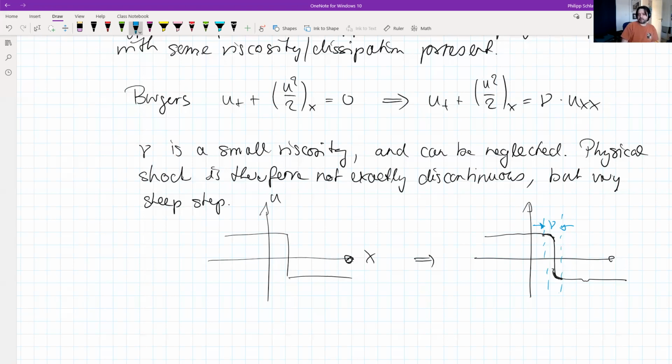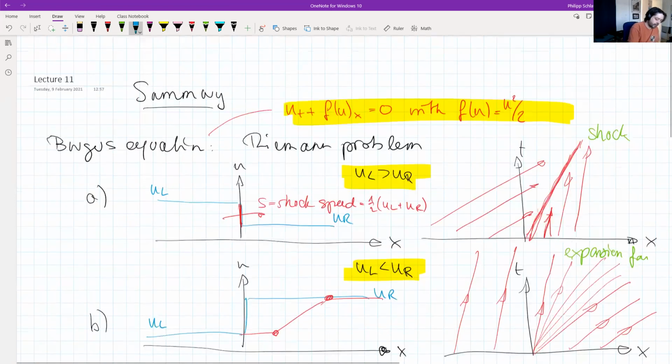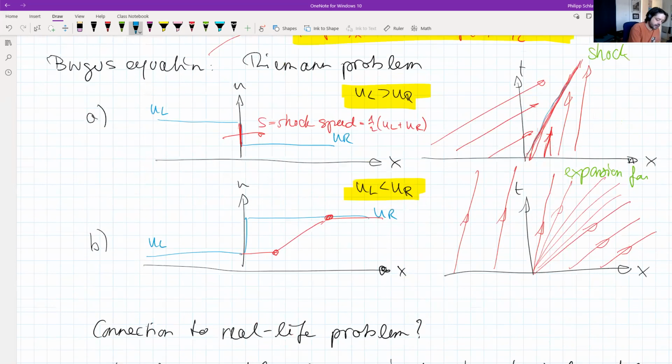Of course, that also makes it important to understand that the second law of thermodynamics, which we used, the entropy condition, that I have not mentioned here, the entropy condition that actually made this shock to be present and here an expansion fan to appear, is really motivated from the underlying physical problem where certain effects happen, maybe the shock when you have characteristics running into each other, but other effects do not happen, namely having an expansion shock where characteristics would emanate out of a shock.